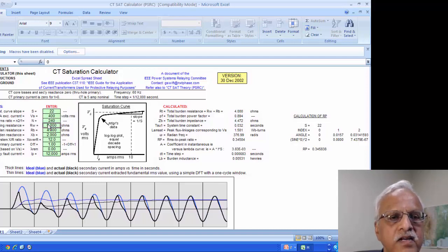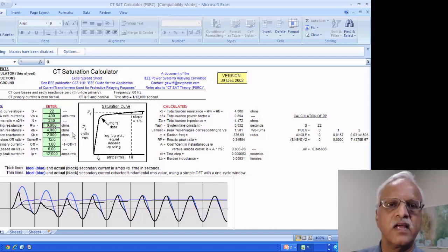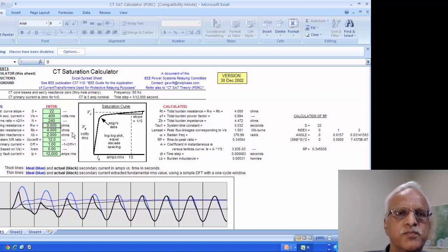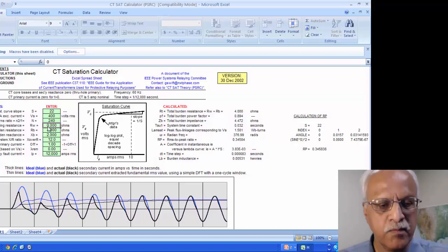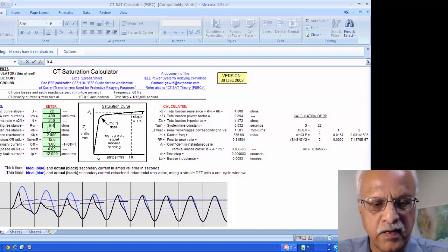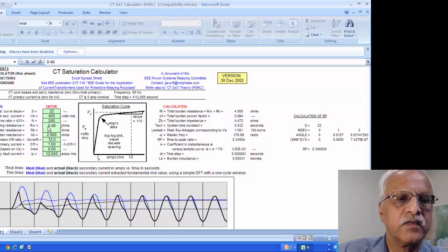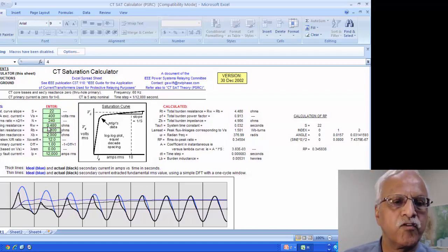And then it has got a winding resistance. Now we said that we typically assume 0.002, but this is specified, or this is already furnished by the manufacturer. And if you look at the excitation curve, they also provide you the resistance of the winding, as ohms per turn. If you assume 0.002 ohms per turn multiplied by 240, it provides me with a winding resistance of 0.48.